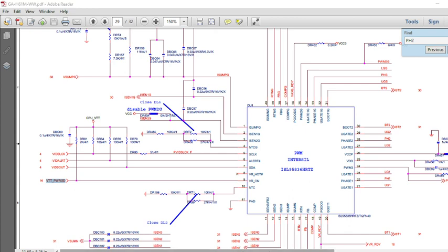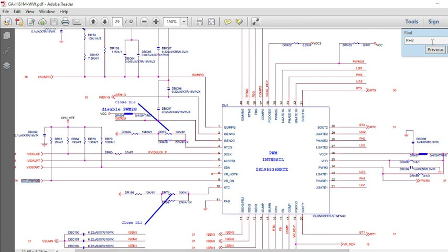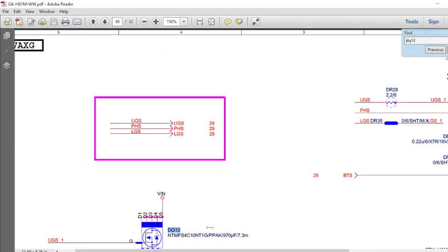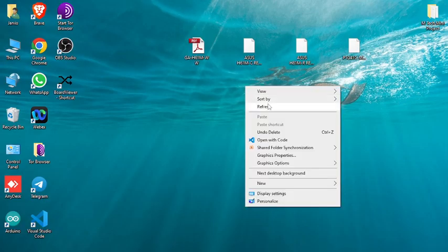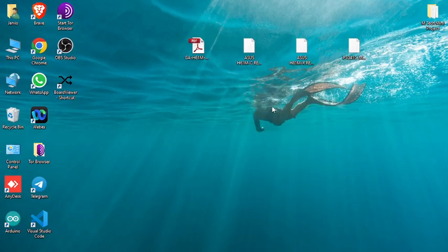Okay, this is the section, and the last signal you have to check is GFX, DQ13. This is the signal where we will check the GFX voltage, which will be near 1.2 volt. So this was the basic in which we learned some voltages regarding H61.